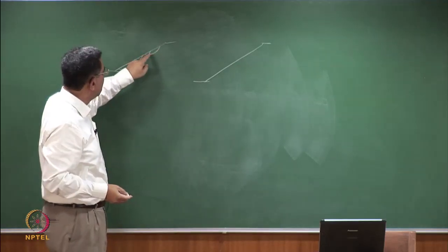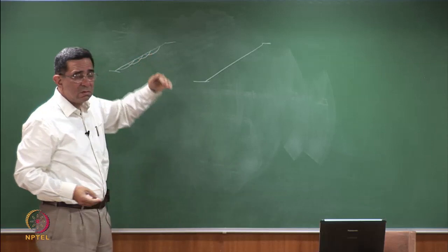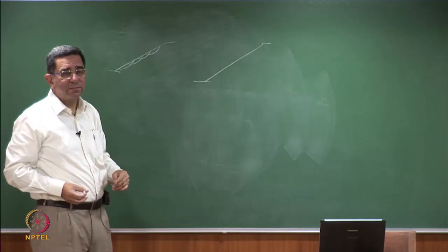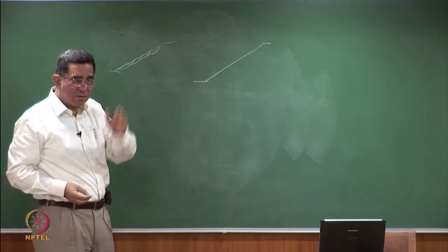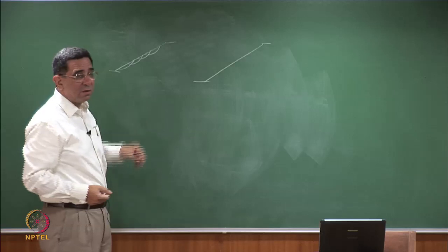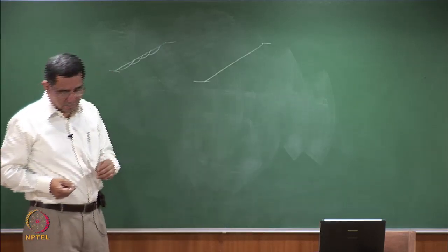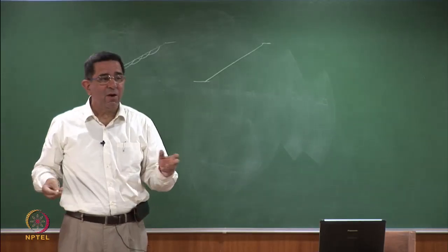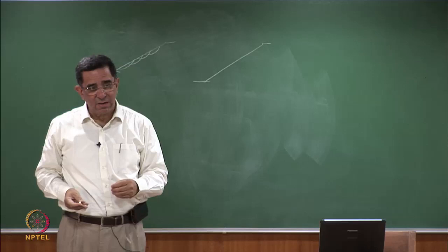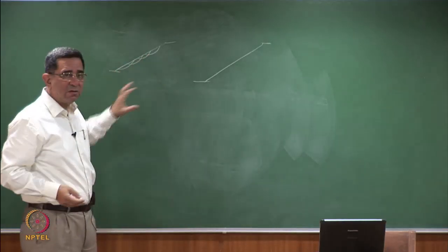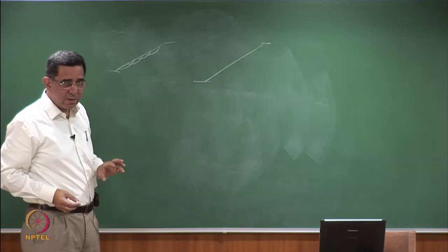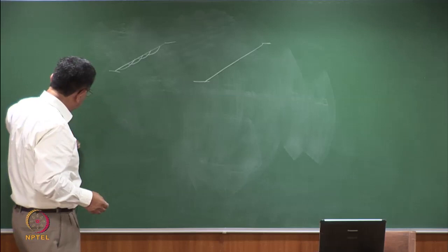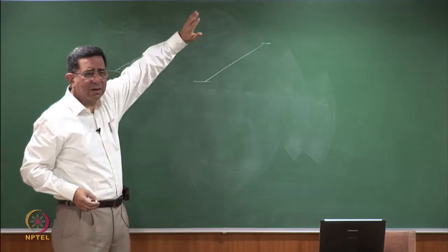As far as this failure surface is concerned, W, what is the downward angle? W cos alpha? W sine is downward, W cos is normal, right. So W cos tan phi is the resistance and W sine beta or whatever is the driving. So all of them have identical values as long as the strength parameters are a constant. So this is infinite slope for these failure surfaces. Whether this exists or whether it exists here or whether it exists there, it doesn't matter.